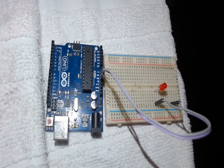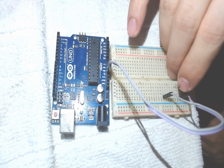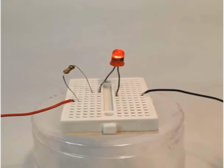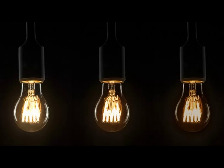But first we have to put a resistor. We can put it between ground and cathode or between the 5 volts output to the anode. This is possible since the resistors are not polarized, so you don't have to worry much about their orientation. And why do we need resistors for LEDs? Well, it helps us to limit the current flowing through the LED. In exchange, it helps us to prolong its useful life. But notice, the greater the resistor's capacity, the greater the restriction of flow of electrical current through the LED will be. Therefore, less luminosity. Then it is necessary to find the appropriate point for the resistor.